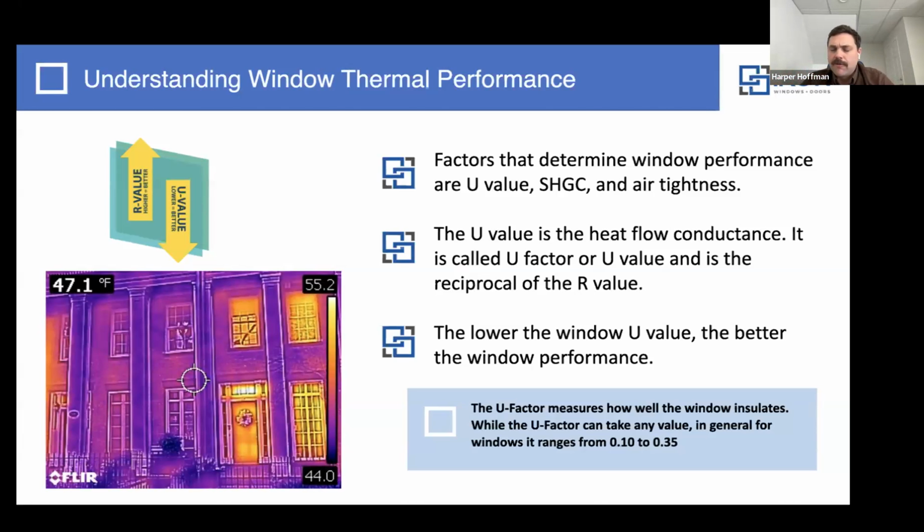So you never really have to know that, or you do have to know the U value. It's a little bit more in depth if you want to know how they come up with the number, which is important, I do believe. And then the lower the U value, the better. That's all you really want to pay attention to. You want lower U values, better performance, better insulative properties. So U value is super important.